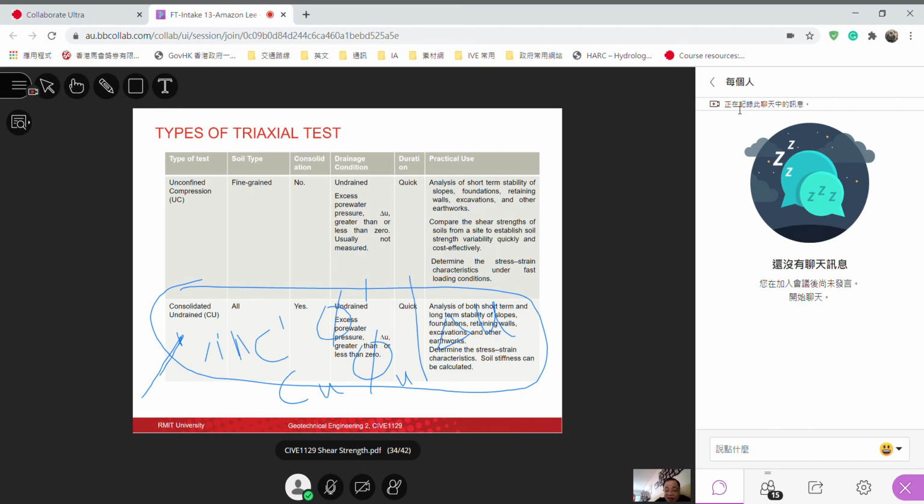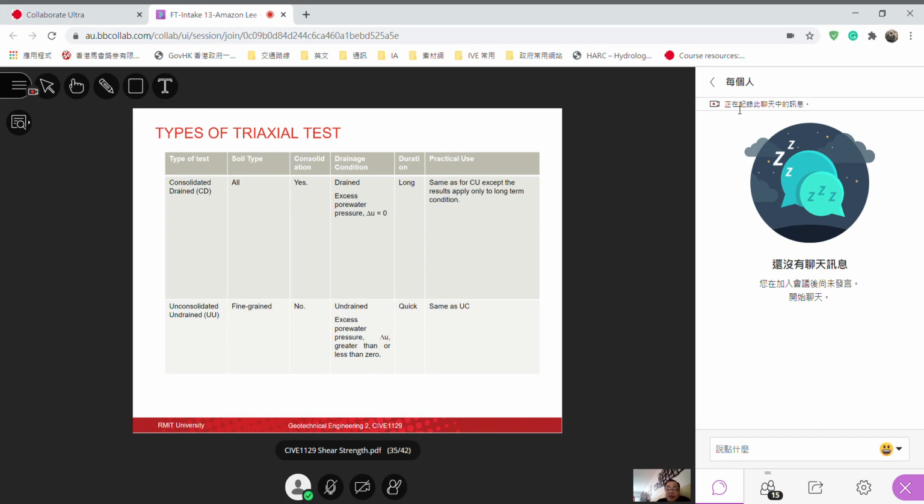Triaxial drained test is a little bit cheaper. It's around $3,000. Some labs only charge $2,000. But it only gives you no information on the pore pressure change. Unconsolidated undrained test is a quick test. Usually, again, it's not too reliable. We may not do it. So by far the most reliable is the triaxial drained test or triaxial undrained test with pore pressure measurement.